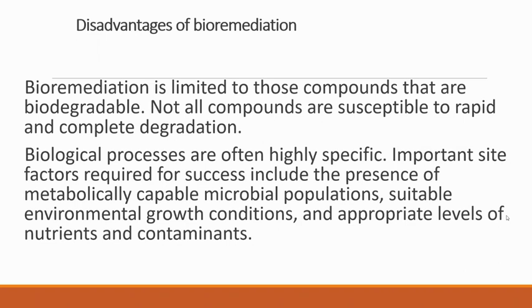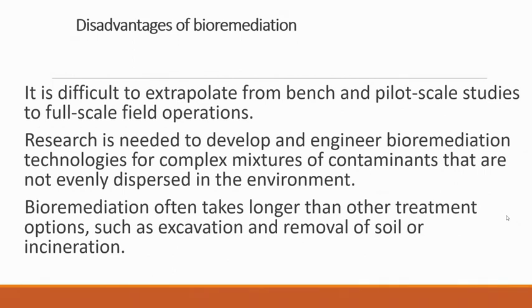So if you don't have enough organisms, the degradation will not take place. If the contamination overwhelms the organisms, degradation will not take place. And then you have to maintain some environmental conditions. Those things are disadvantages of bioremediation. It is difficult to extrapolate from bench and pilot scale studies to full scale operation. Research is needed to develop and engineer bioremediation technologies for complex mixtures of contaminants that are not evenly dispersed in the environment.